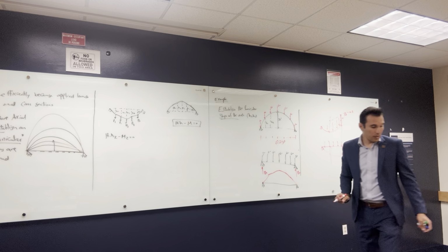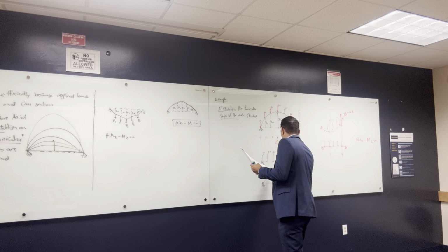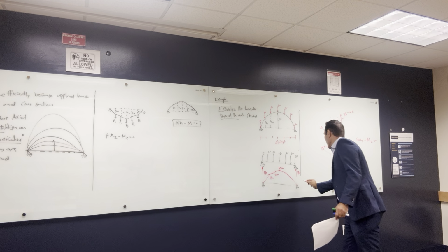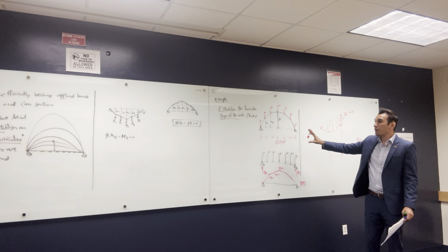So the bending moment is going to be something like this, and when you find the values, it's 4,500, 7,200, and here 8,100, and it's symmetric. Okay, that's the bending moment diagram of the equivalent beam. So it's very easy to do.